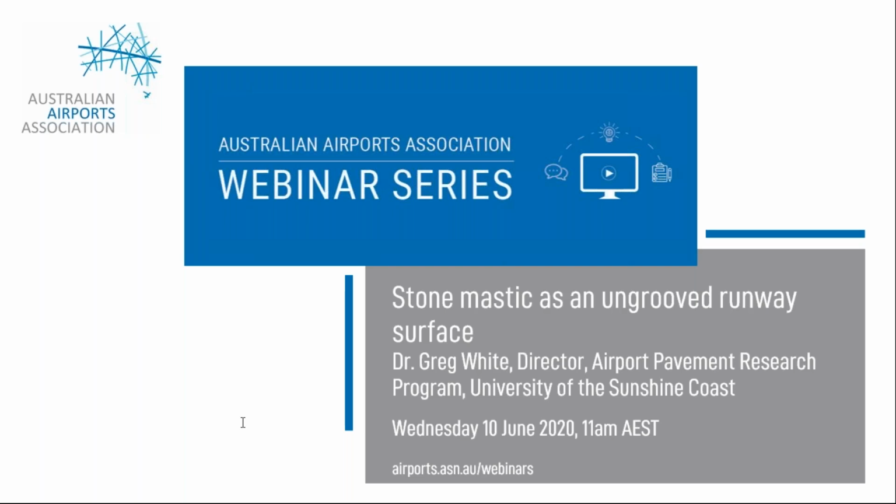Having said that, most of our airports don't really groove for wet weather friction. They groove to meet CASA's regulatory requirements. So we're essentially grooving most of the time because we can't achieve 1 millimeter surface texture.